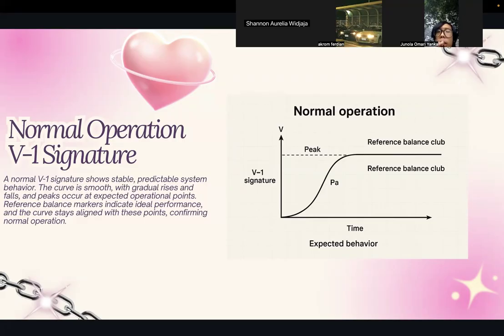The VI signature starts at 0 at t equals 0, and as time goes on, the voltage increases exponentially and then logarithmically, and then it plateaus. So we can use that peak as a reference, like the forward voltage, so that we know in the future whether or not it is higher or lower than the measured voltage that we got from the baseline voltage.